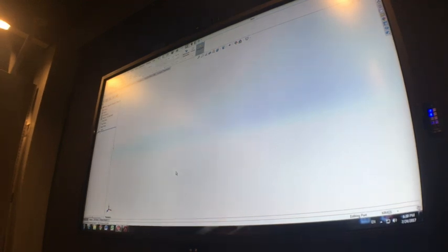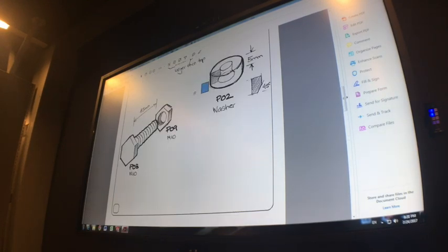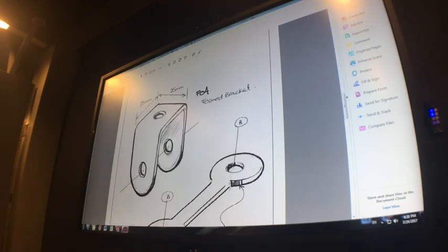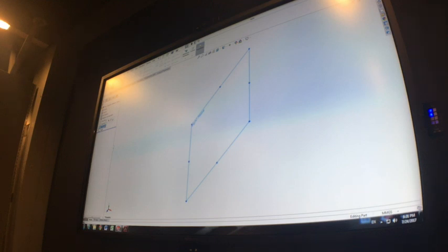I've seen some people sketch this or make this part already. I'm not sure which plane you sketched it on. If you remember when we did this one here, we did it on the side. But it was standing up. We want to do the same for part 5. If you've done it lying down, it's not a big deal. We'll see how that affects things when it comes to the assembly. We'll fix it up then. So don't stress about that. But if you're starting it from scratch now, start it on the right plane with a new sketch.